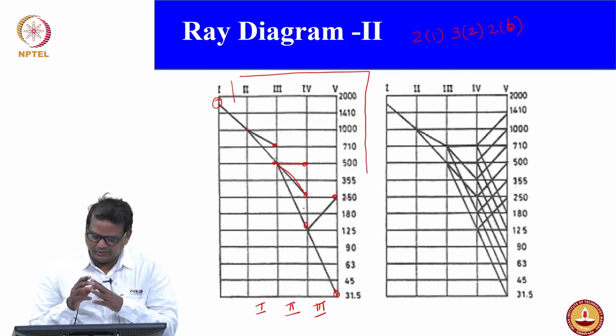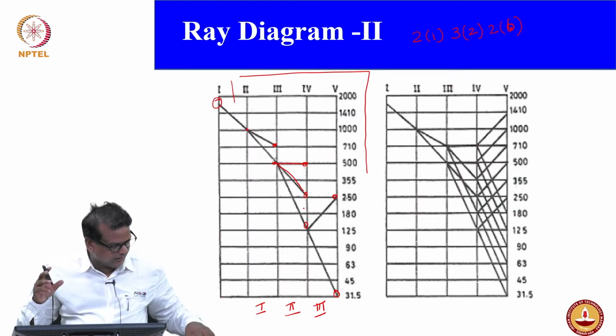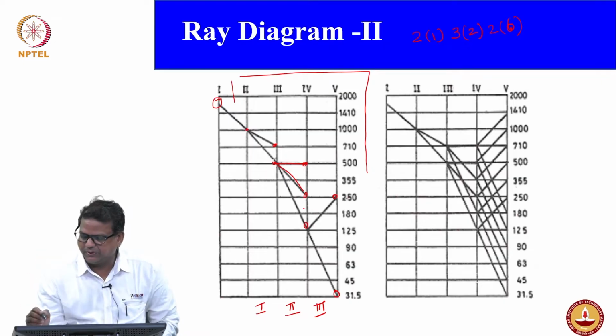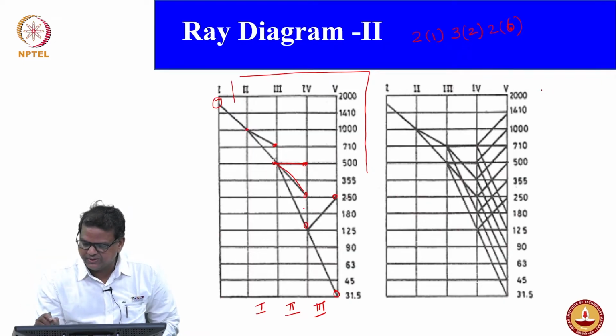Also, as I said earlier, it has to follow the optimization aspect, particularly the I max and I min aspect. Except for the first stage, all other stages should have the gear ratio I max, that is N max over N input speed, less than 2.